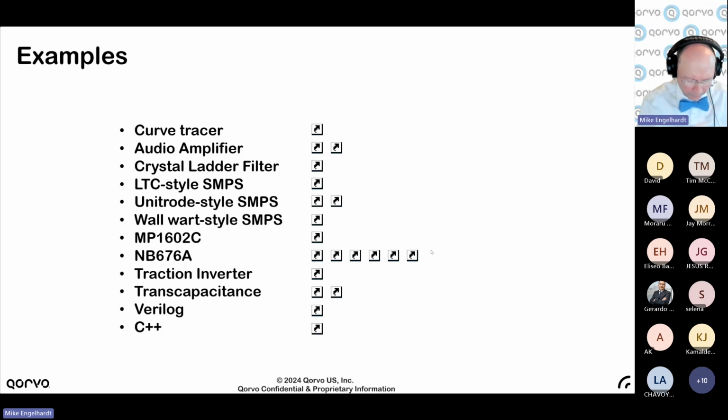When you make a sub-circuit, usually the models necessary for transistors are inside the sub-circuit. So if the model is implemented as these things normally are, that's usually not a problem. I will show how to import third-party models. I'll say a couple of words about it now because it's so important. It really doesn't matter which simulator you have. You're not going to have models in the simulator for everything you need.